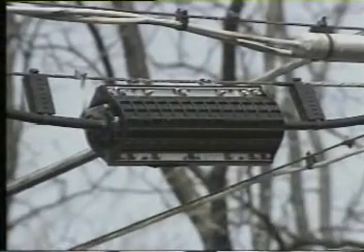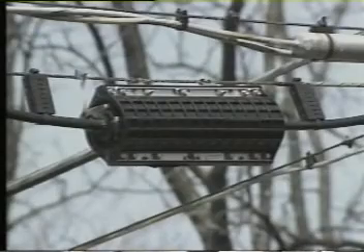This aerial cable connects through that interface box on the customer's premise to a small cable which goes up to the telephone pole. Now, because of this hanging from the upper to the lower, this is often referred to as the customer drop. Usually, you'll find 2 or 4 pairs of wires inside this little cable attached to the customer's property. Once it gets to the telephone pole, you'll find that it probably connects to an even larger cable in a fairly large plastic or rubber enclosed encapsulated splicing area. That can be opened up and the customer's individual lines can be attached to the cable that carries other customer lines in that area. This larger cable then usually proceeds along through some other series of poles, and at some point it will probably go through an armored cable down under the ground and be carried back to the central office.